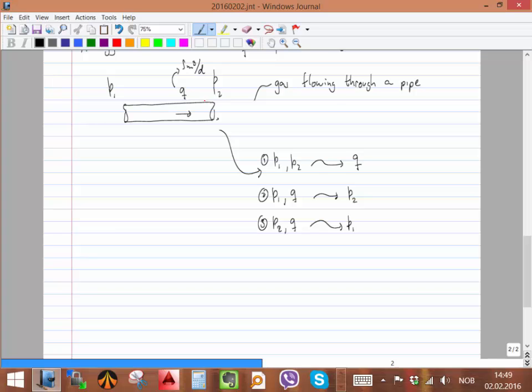So in general, the total pressure drop that we have in this pipe is a mixture of three parameters. We have dP/dx of friction, that means the pressure losses that you have against the wall. The fluid is going fast and going against the wall and is causing some friction, some energy and temperature increase. Then we have some other type of losses that are hydrostatic. And we have also acceleration losses. This x is referring to the direction and coordinate system along the pipe. Acceleration is due to sudden expansions and contractions in the pipe.